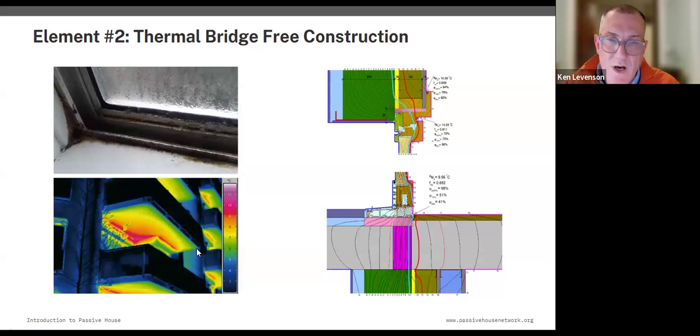We want to align that insulation. So you can see the thermal lines coming through here where this door is aligning with a break in the slabs with insulation going to the exterior insulation on the wall here, and then connecting to the exterior insulation here. So all these things in terms of the detail and how things are aligned and come together is something that we look at carefully.